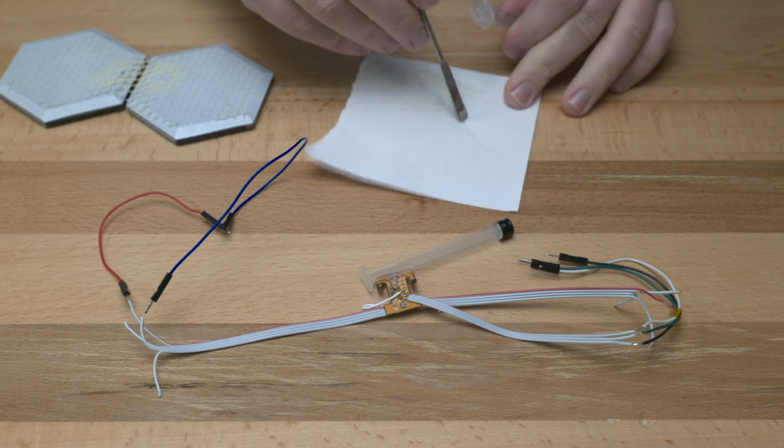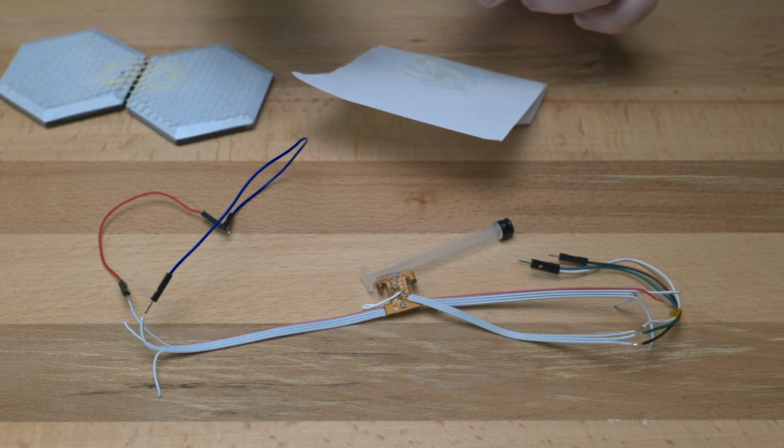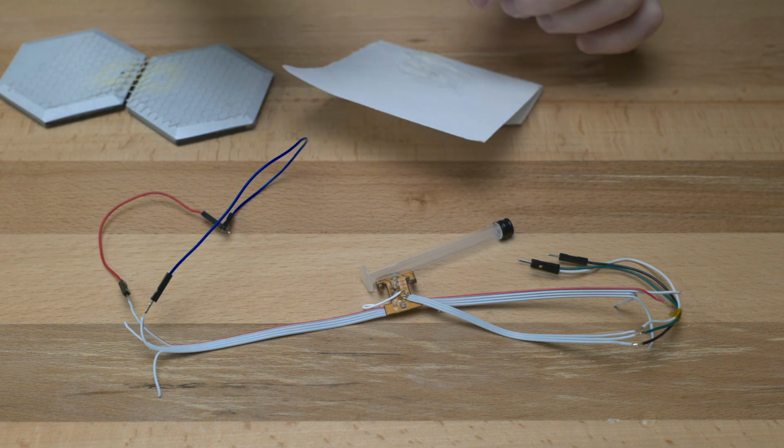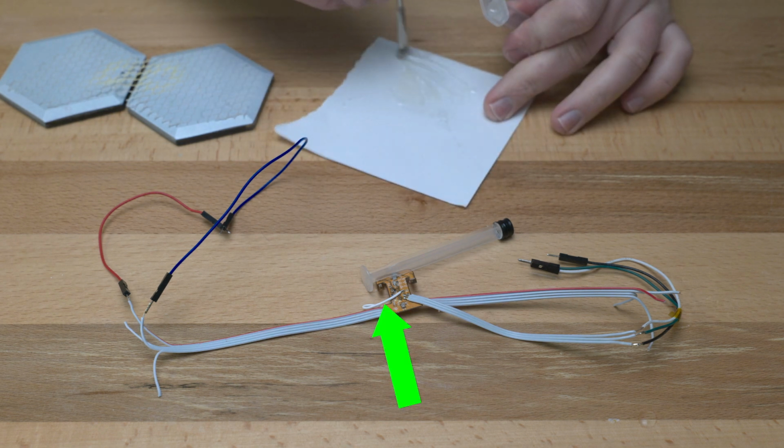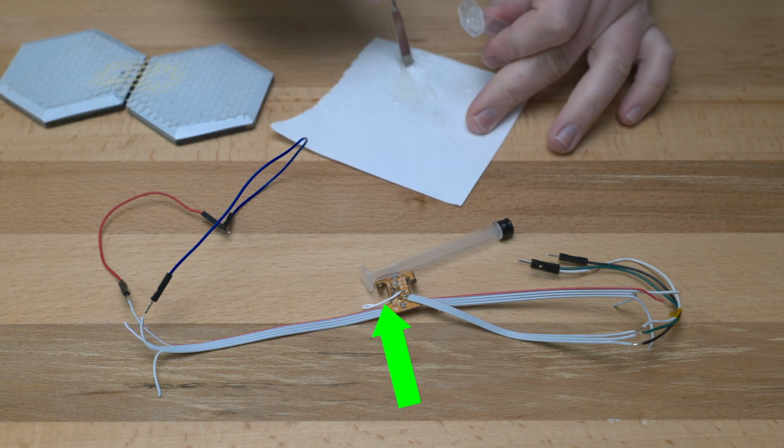Now, this ETR trigger pin is only mapped to one external pin on the microcontroller, and I wasn't originally planning to use this mode. So when I made the circuit boards, I didn't wire it up correctly. Now, if you watched the last video where I discussed making the boards, you might remember that I broke out the extra pins to test points, just in case. Well, I got really lucky here, because one of those unused pins was the ETR pin. So I was able to just add a small white wire to get the LED signal where I needed it on the microcontroller. Once I got this white wire and the code implemented, I checked it out on the oscope.